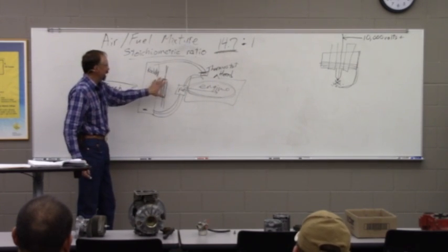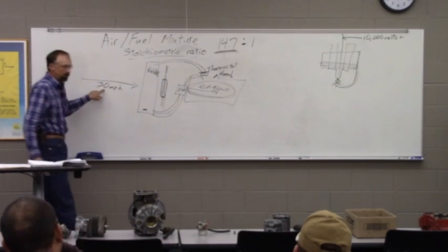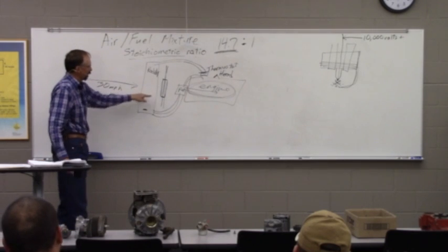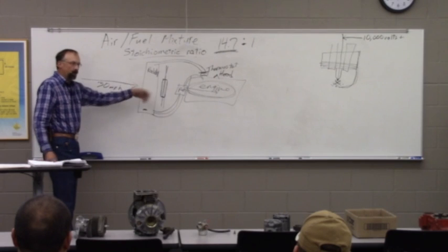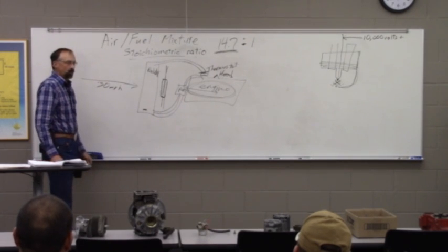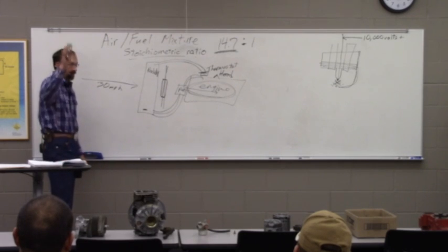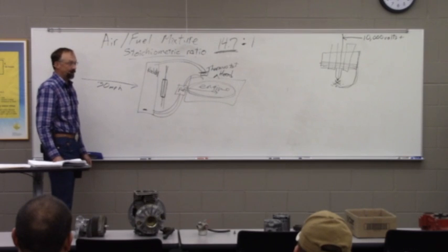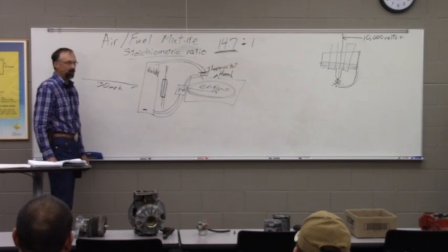And when that fan is actually necessary is when you have less than 30 miles an hour of airspeed going through the radiator, and you need to get some airflow through it to have some cooling. So, for example, when you're on the highway headed from here to Cheyenne, and the wind isn't going the same way you are, and you're driving 60 miles an hour, you won't be able to tell the difference if you have a fan or not, because it's doing nothing.